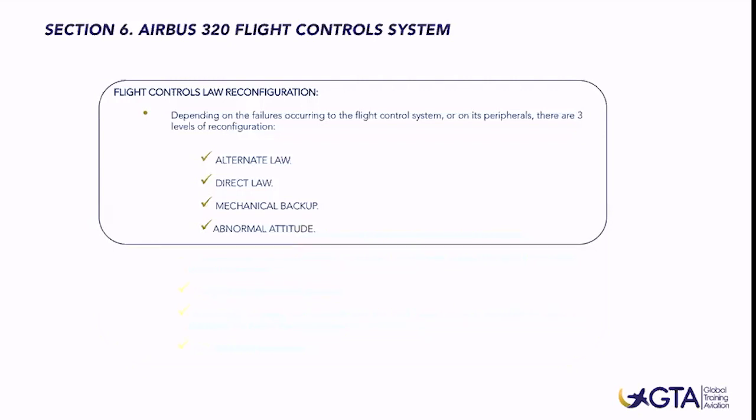We don't have any pitch attitude protections. We don't have any high angle of attack protection, but we have something similar, which is called low speed stability. This artificial low speed stability replaces the normal angle of attack protection. And the pilot will notice a progressive nose down signal, which is introduced and tends to keep the speed from falling below these values.